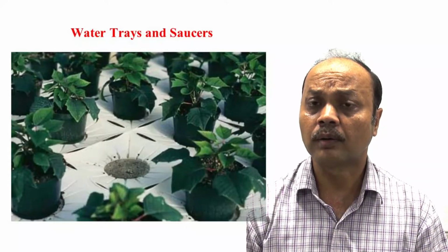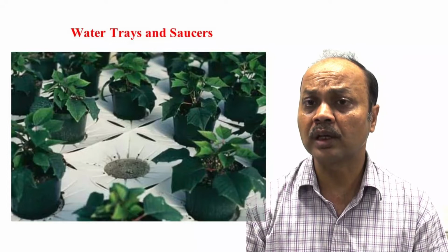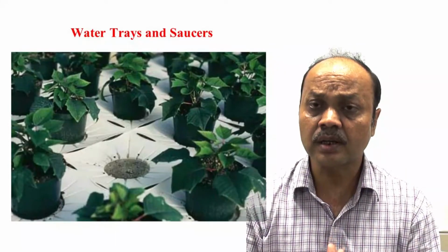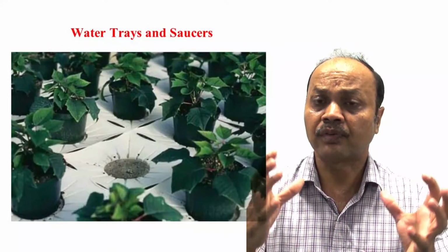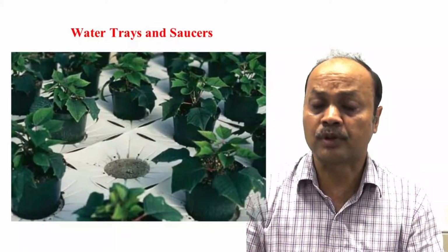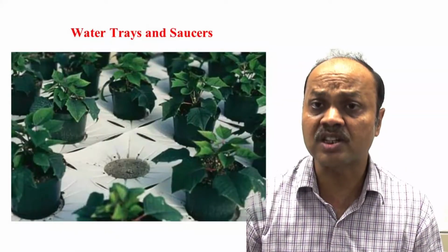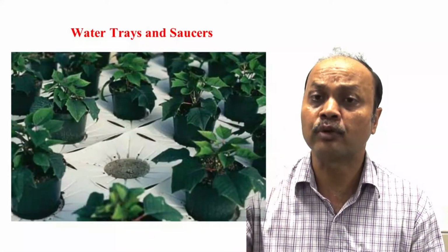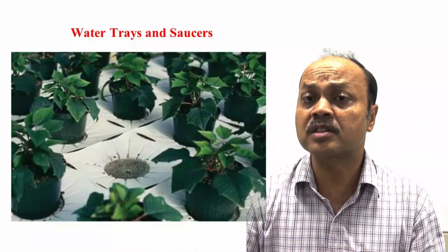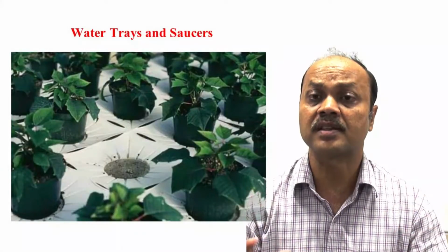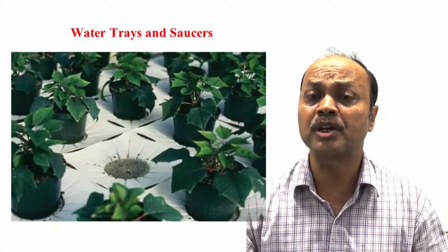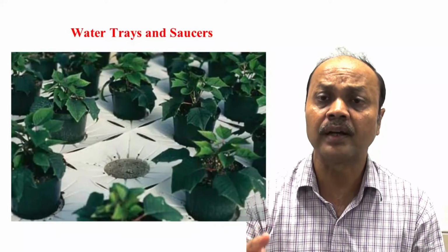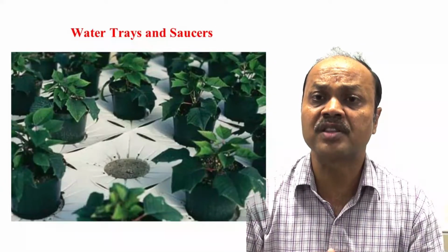As I told you, in summary, what are the important lessons you have learned today? Basically we have to think first about how to conserve moisture, right? Earlier you discussed water harvesting. As I suggest, you should not use groundwater, okay? So you go for rainwater harvesting, then use the micro irrigation system. But if you are using a micro irrigation system, the design of the system is very essential. That is not very tough. Based on the crop spacing, which crop you are taking, your water requirement will be different, plant to plant, row to row spacing, right?